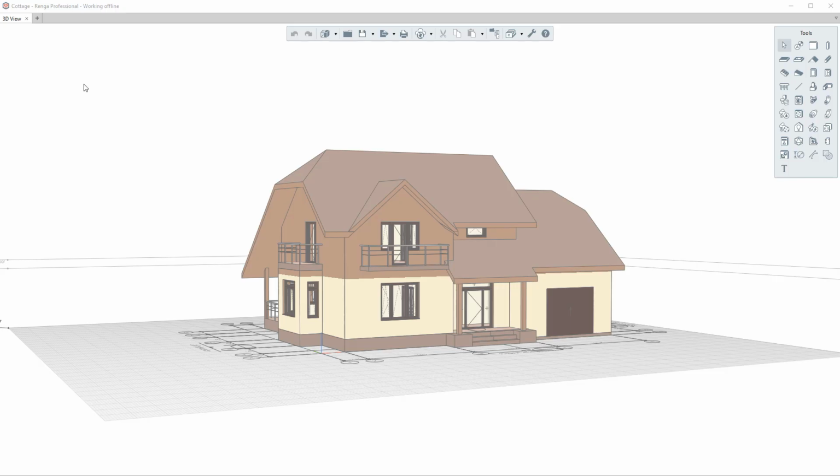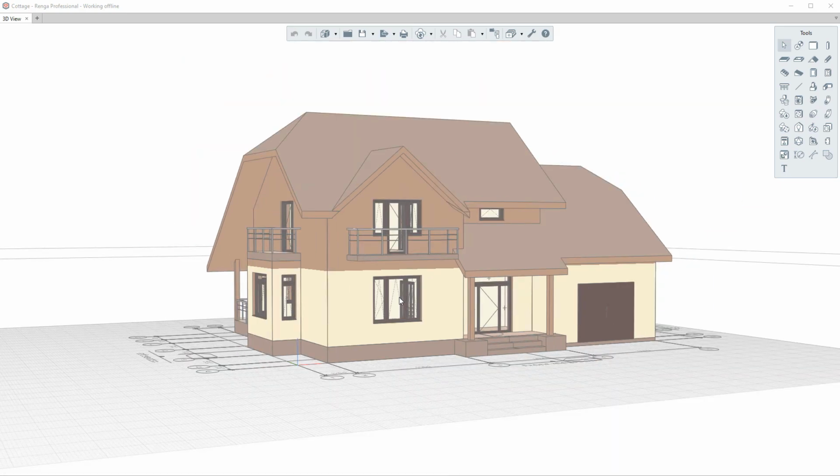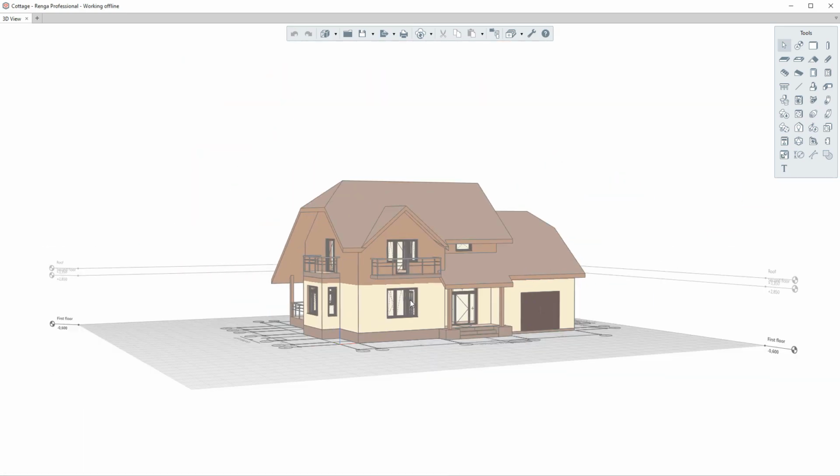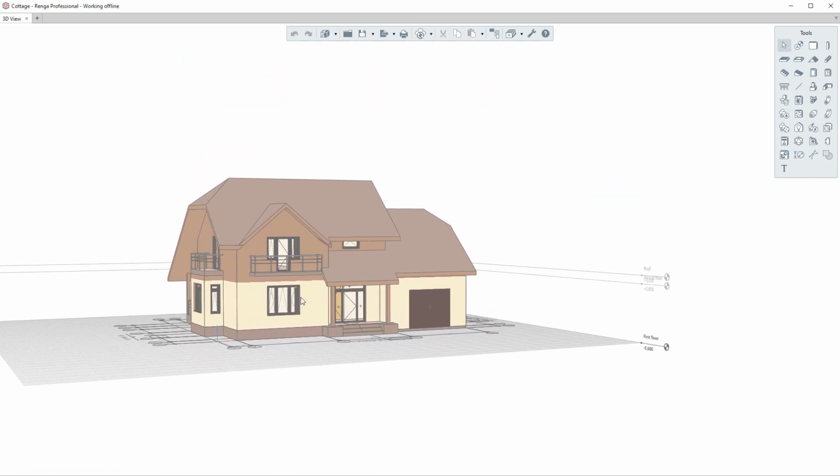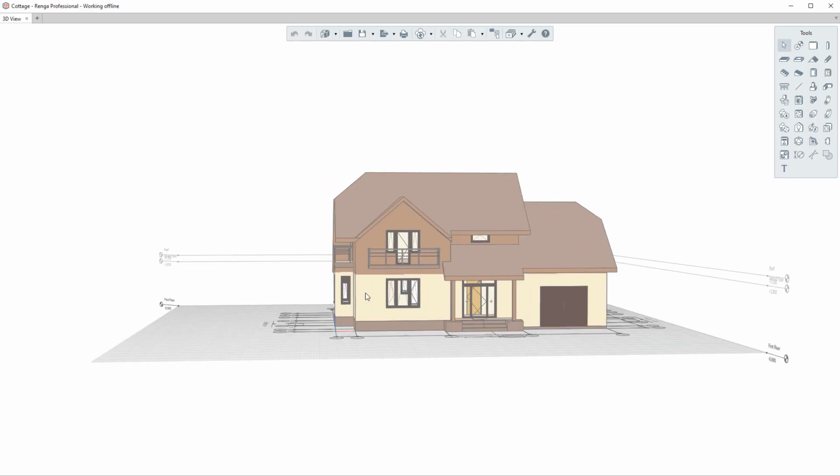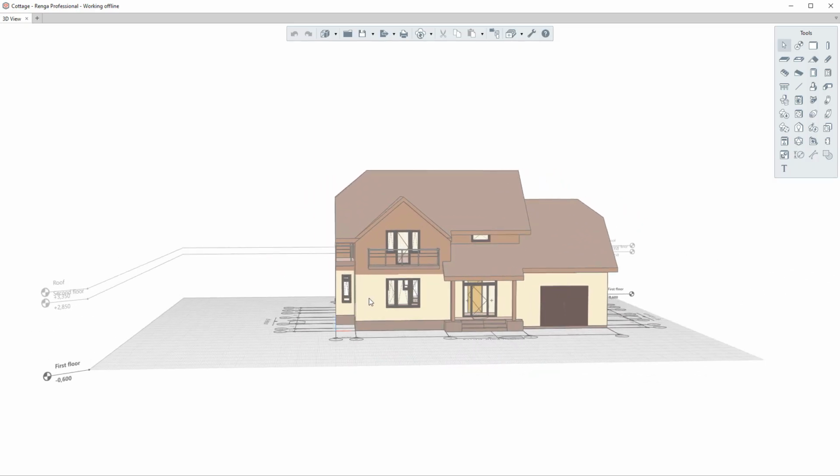There is very simple model navigation with just usual 2-button mouse with a scrolling wheel. To zoom in or zoom out a view, use the mouse wheel. To move the working plane, hold the mouse wheel. To rotate the model in 3D view, hold down the right mouse button.